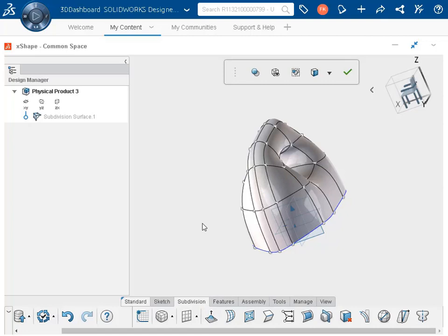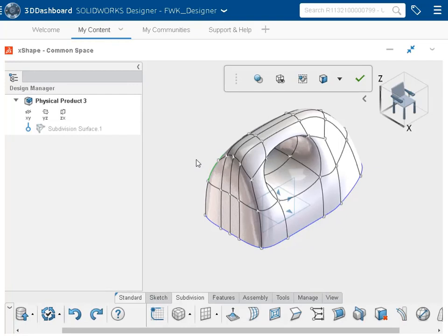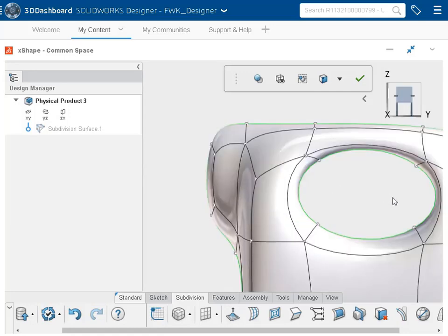After making a few more adjustments, we'll use Extrude in a different way with a different toolbar. Control-select the two rear faces and then click Extrude from the Quick Command toolbar. An extrusion combining the two faces is added. Here's another great option, aligning a set of vertices to align.